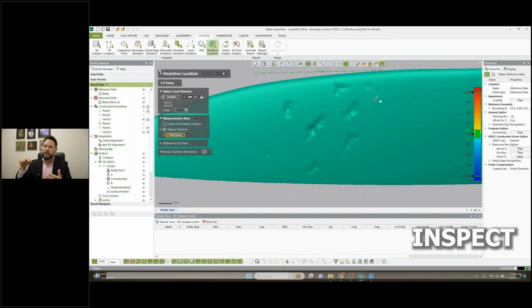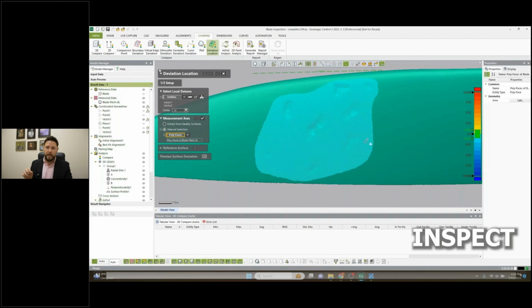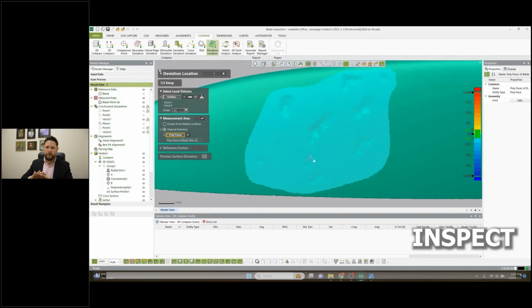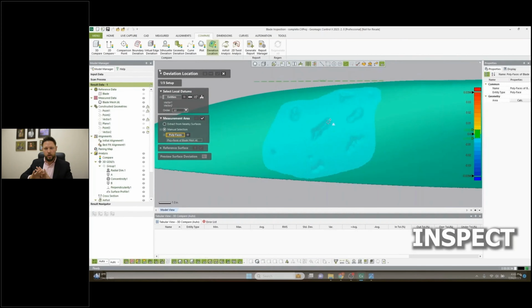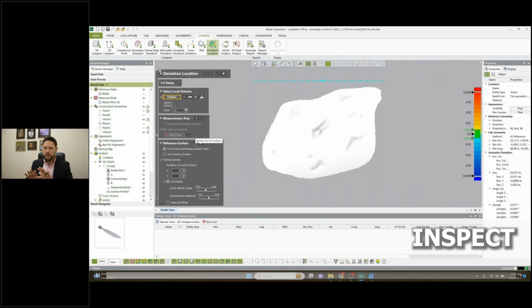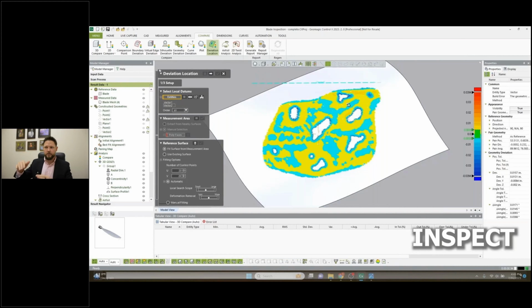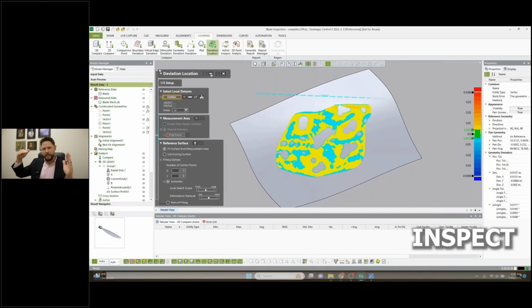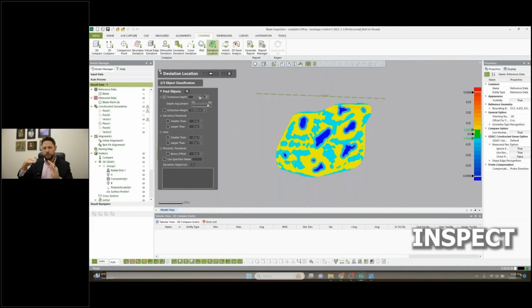So we can come in and select the area specifically that we want to analyze. This tool is going to put a virtual surface across the airfoil surface and then measure those deviations back to that surface. I've got some vectors: the front of the airfoil and the end, the overall length, that end point is a reference. So you'll see we'll use those in a second.